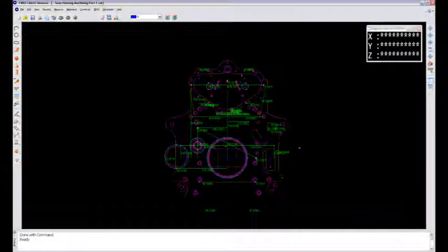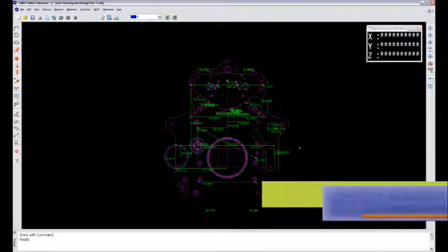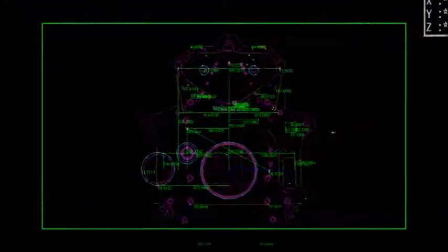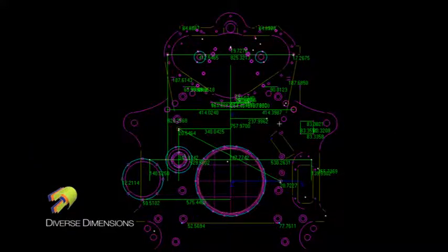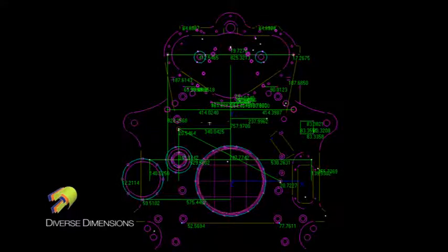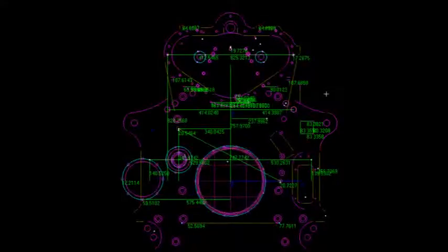In this module, I'm going to talk about custom measurement, measurements that are taken on some of your parts that don't necessarily need to be taken with the Faro arm. Say on this drawing here, or on this part here, it's a casting that went through a machining process, but maybe on the drawing there's a dimension from this radius, or this part of the casting, all the way back to this part of the casting. And the tolerances are so generous on the drawing that we can get away with putting on a tape measure just to check that out.